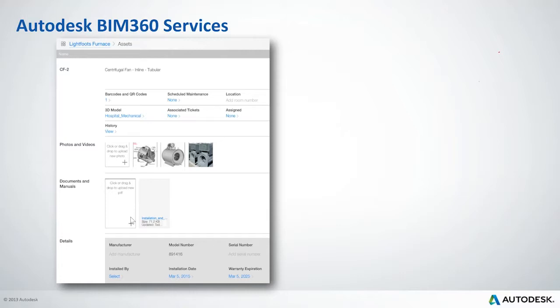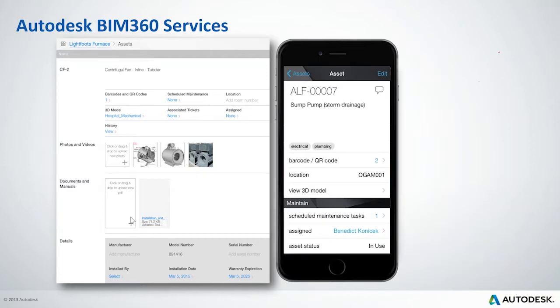But when you do it like that, and if you go from Revit to Field, you can check the status of it, and you can say that the status of these things is installed. And from that status, the model can be controlled by color. So if you said, show me the pieces of equipment installed in green, Revit and Navisworks can respect that data from Field and show you things installed as green, and things that are not installed, maybe on back order, in red. So there's a nice workflow on the data.